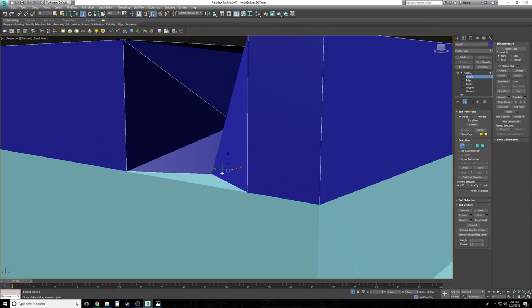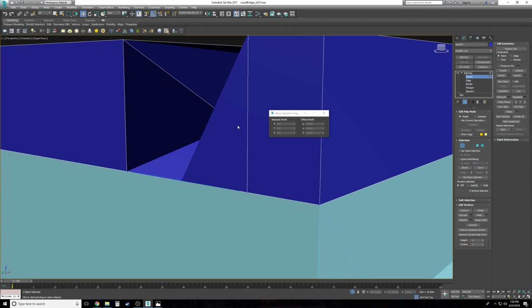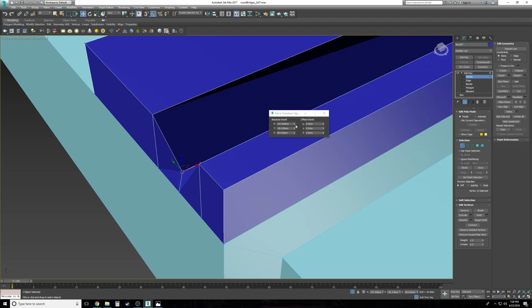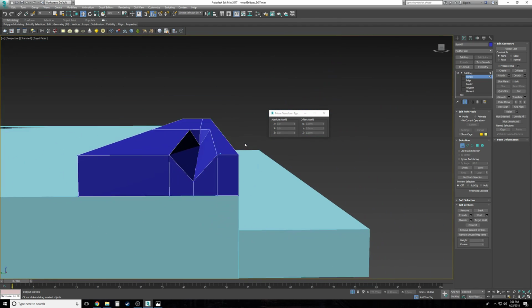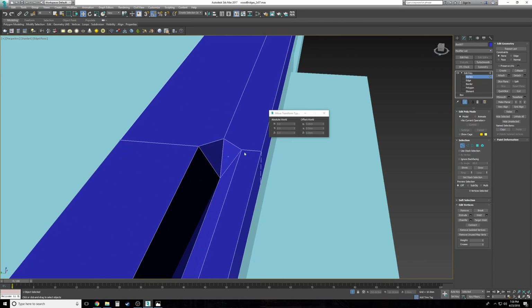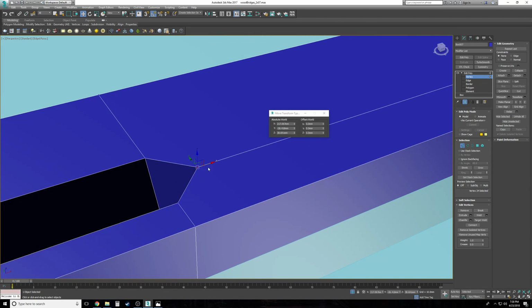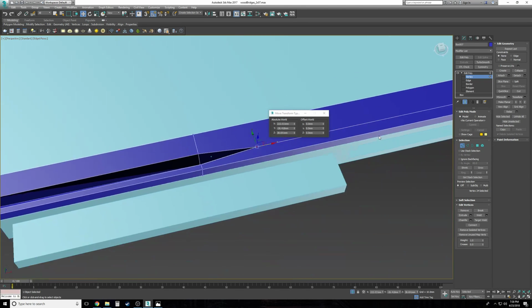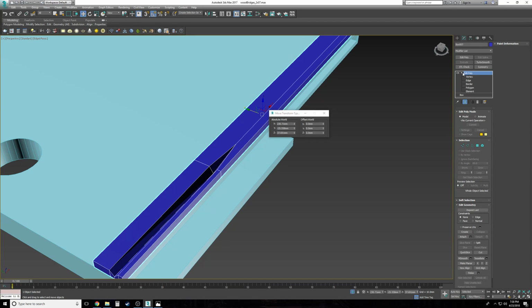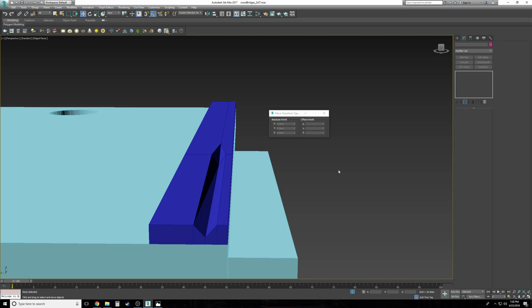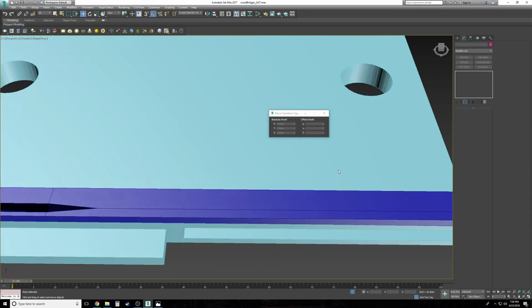I want to bring this back out because this is going to be flush. Let's see, that's x-axis. Copy and paste that. And I want this to be as well, because I want the piece to be on the top split, not the bottom. And now I want this to all be conjoined. You can basically just pull it out more like that. Yeah, see, that looks like a legit split. Maybe a little too big, but we're printing, so we want to make it a little bit exaggerated as we go.